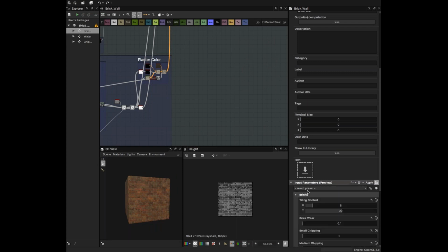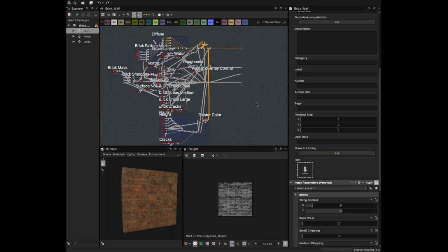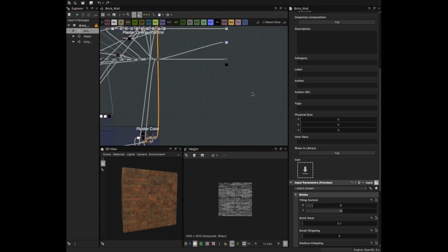It took a while to open, but there are some parameters that you guys may want to expose, and this really goes for your personal ones, but if you get ones off Substance Share, if they come to this level of detail, you can certainly go in and expose your own parameters if there aren't any exposed, right? Especially since it's not your own graph, you may not want to constantly be trying to search where that tiling section is in the graph. So do it once, expose those parameters, and you don't have to do it again.